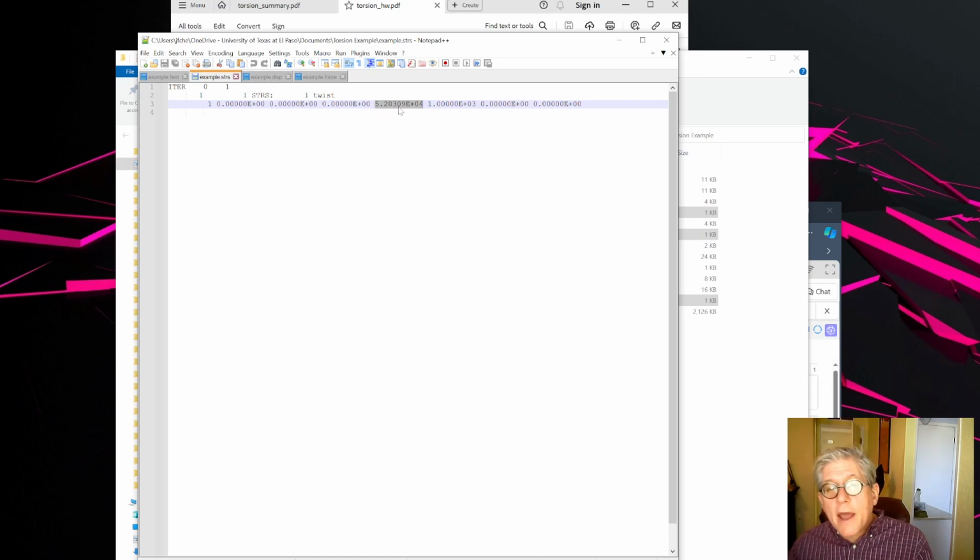Now this is the one that actually correctly calculated with TC over J. So this is part of the issue with why we need to look at these in this file. In the post-processor, at least the HyperView, it doesn't seem to want to show those values explicitly. It'll put it into the effective von Mises, but not that one, okay?